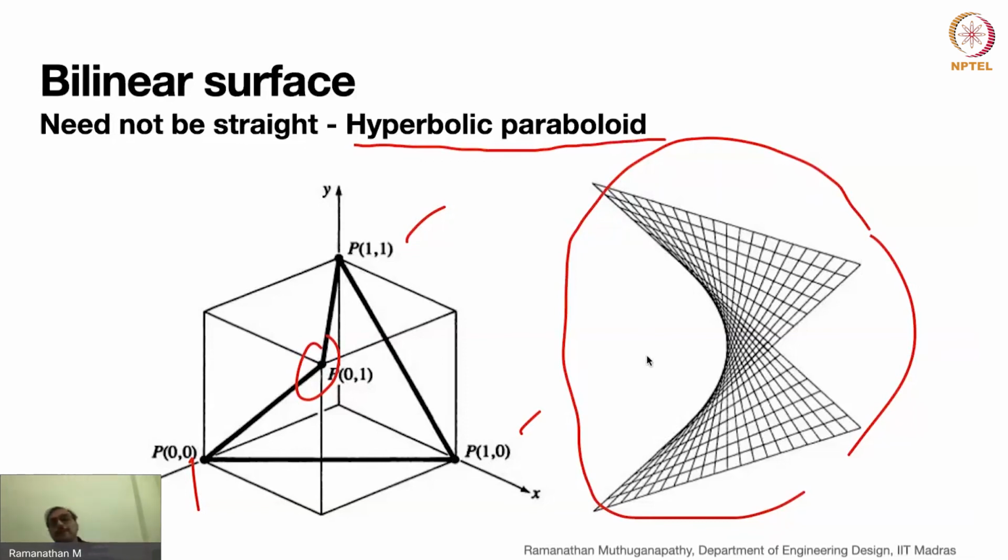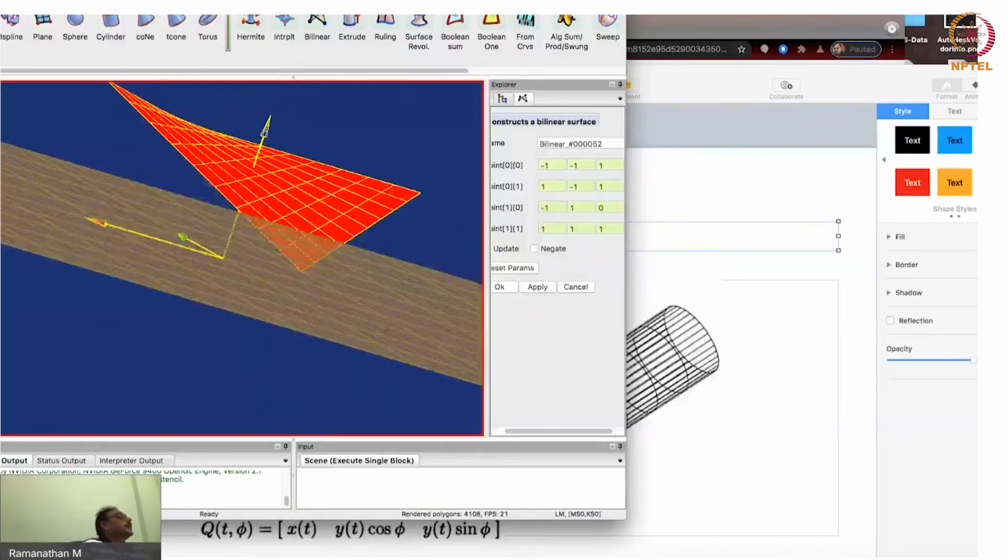So this is a simple linear interpolation on both parametric directions. Did you guys observe that? Can you say something, please? Yes or no? Yes, sir. Okay, good. Because I'm switching between these two, this is very simple linear interpolation, and you see that you can get a really highly curved surface by a simple technique. You just do linear interpolation on either side, and that is all. A very simple procedure, and you get a parametric surface called a hyperbolic paraboloid. So that is the greatness of using these parametric models.